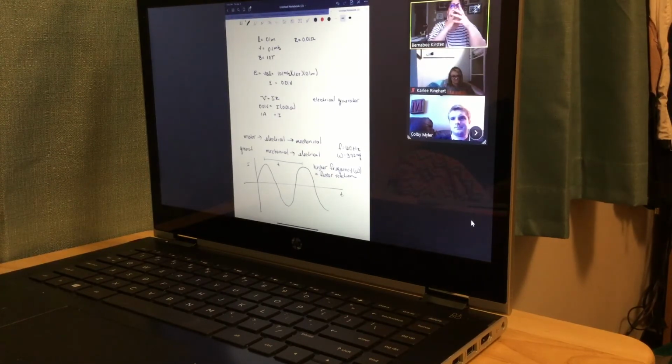Another way of doing this is, instead of rotating the square loop, that can stay stationary and you can move the magnet around it. You get the same effect. But you wouldn't want to use just chunks of iron or anything like that, because you need to have a stable, constant strength and constant direction field. So that means an electromagnet.